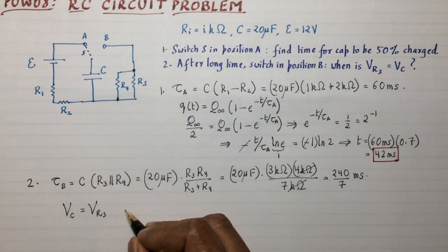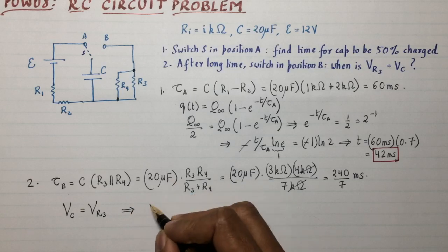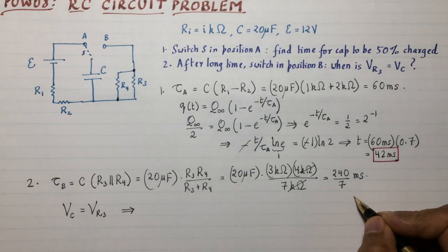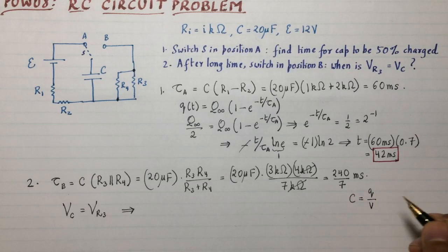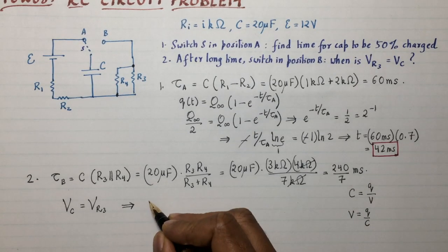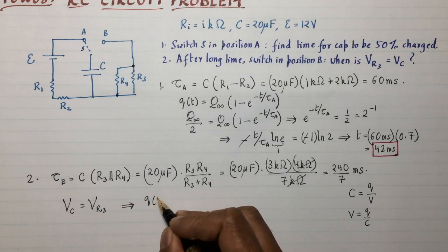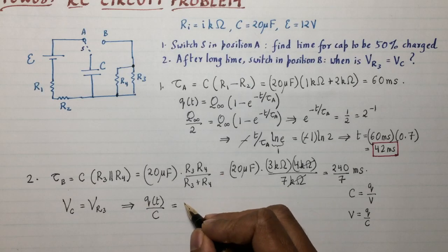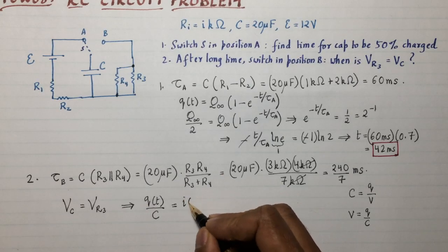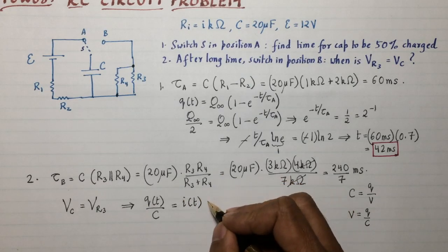The voltage across a capacitor is found by remembering the equation that governs capacitance. Capacitance is charge over voltage, therefore voltage equals charge divided by capacitance. Now the charge as a function of time for a discharge circuit must be used, and that should be equal to the current as a function of time for the discharge circuit times the resistance by Ohm's law.